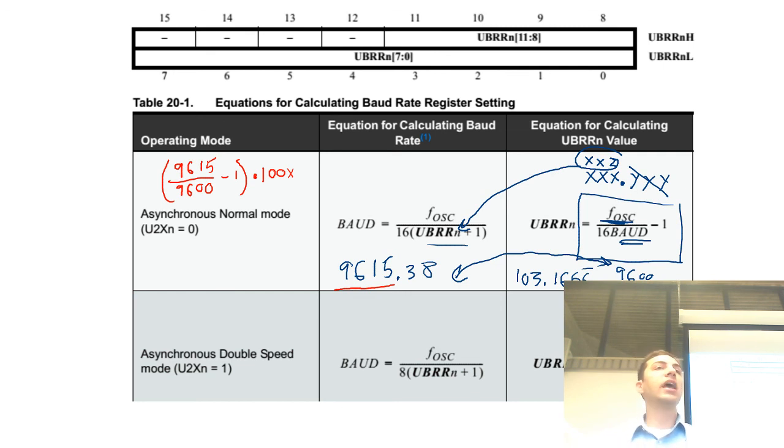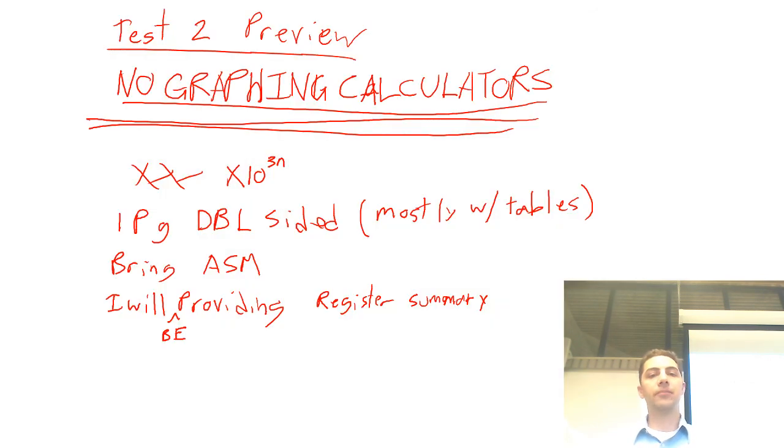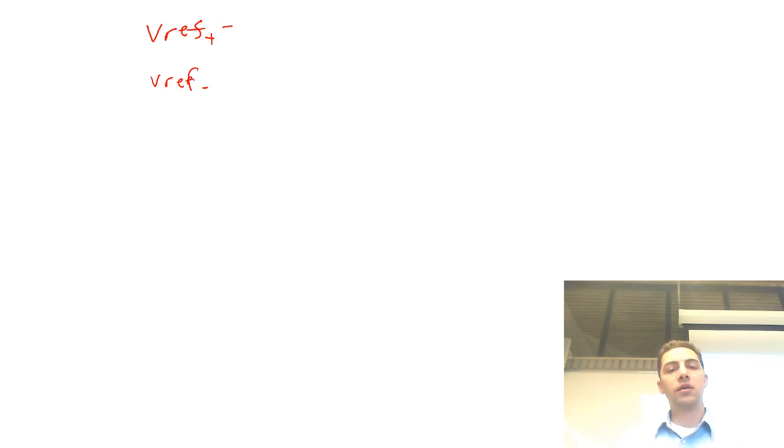I think perhaps ADC resolution might be something you want to go over. Let's think about that for a second. Because for a given VREF, especially if we have differential, your VREF would be something like 5 volts. Your VREF negative would be something like 0 volts. You could have something that is a differential measurement, or you could have a different negative reference. Most things are ground referenced.